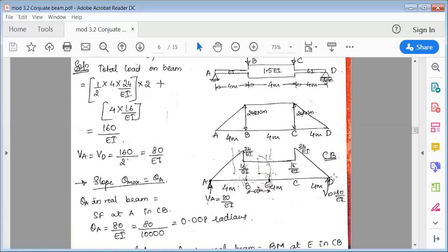Once you draw this, just join the diagram. Okay, after this, join all the ordinates. After this, this is M over EI. For this, you have to add conjugate supports. So these are the conjugate supports. In the actual beam, it is a simple support. In the conjugate beam also, it becomes a simple support as such. Same thing here also. It remains a roller support. Roller is nothing but again only one reaction. So only one reaction will be shown here.